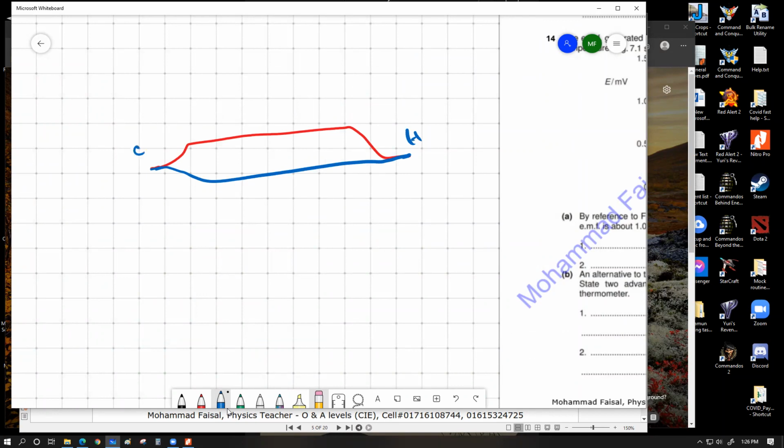And whenever there is a temperature difference between these two junctions, if we place a voltmeter anywhere in the wire, over here, in some cases we can also choose to attach a voltmeter just like that. I mean, the cold junction itself can be the voltmeter, so you can even connect a voltmeter right over here. So the voltmeter itself works as the cold junction. You don't have to place it over here. That's going to give you the voltage measurement, which needs to be converted into the temperature of the hot junction, actually the temperature difference of the hot junction.